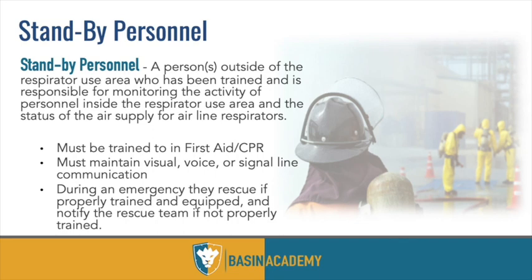So, standby personnel, I mentioned these in brief. This is the guy who's working outside of the red area or the red zone where high levels of H2S exist. His job is to rescue if somebody were to go down. He's not to be on his phone or doing something else. His job is to be focused on the people working in the H2S area and be ready and equipped and trained to provide rescue if necessary. This may be done by means of a rope. This may be done by means of going in and grabbing them, a winch. There's many different ways to rescue, but this person's job is essentially to be prepared to rescue in the event of an emergency.